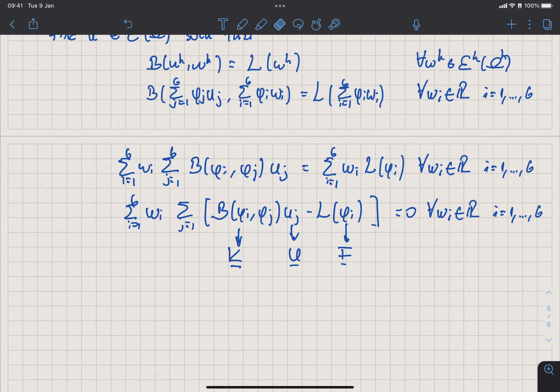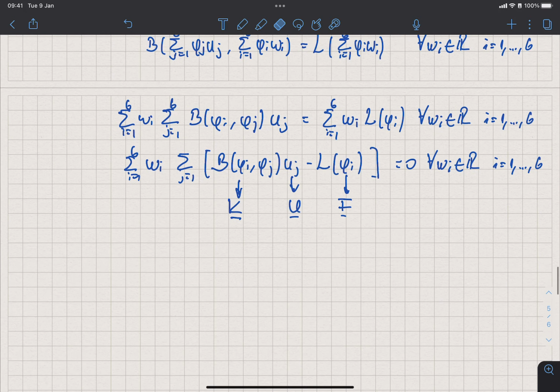So that's going to be essentially one row, and then you take j equal 2 and so on, and so this leads essentially to our system KU equals F. So I'm going to put here KU equals F, which we solve for our degrees of freedom, and again I'm using uppercase U here to show that this is a vector that contains all the displacements of the nodes. Yeah?